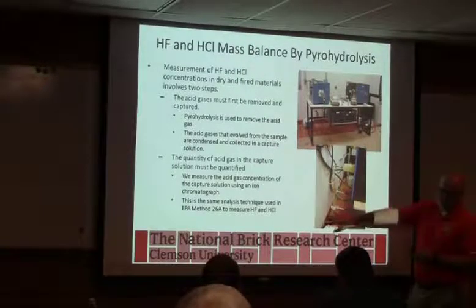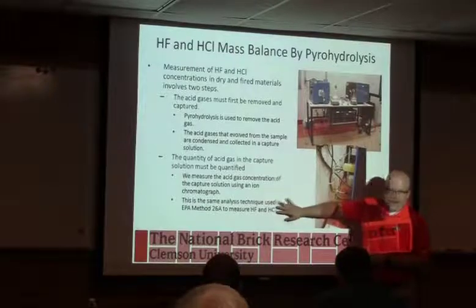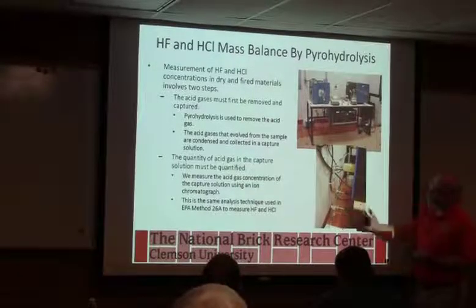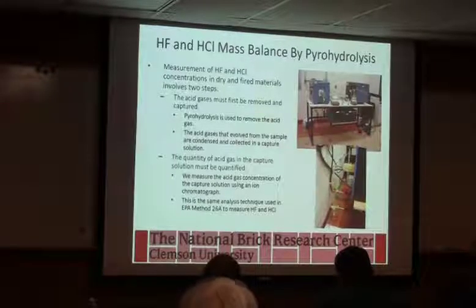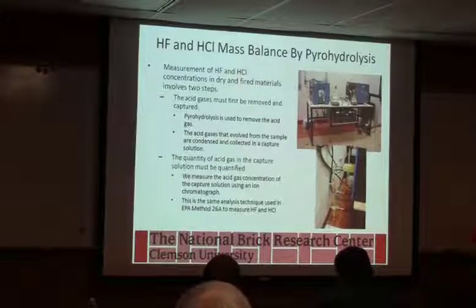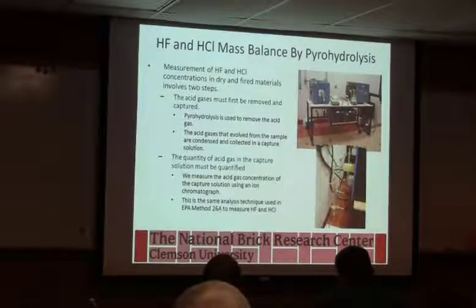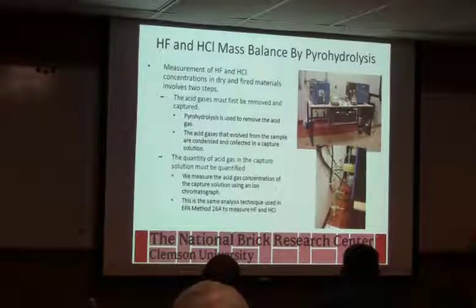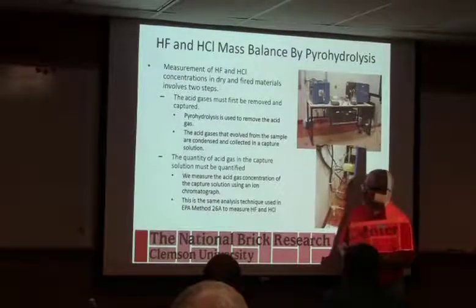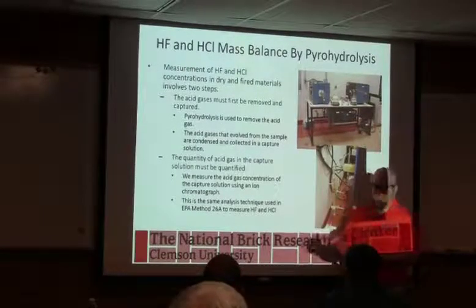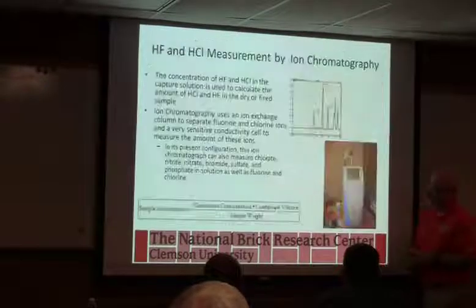So new kilns that are very good at controlling air, no leaks, we can get correlations of up to 99% between what we measure in the lab and what the stack test says. The older the kiln and the more air leaks there are, the more dilution happens, and we tend to always be a worst case. So we're saying we can give you a number. It's like it'll never exceed this, basically.